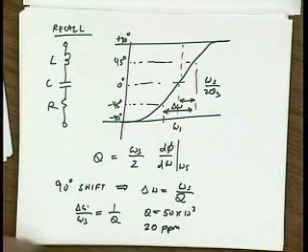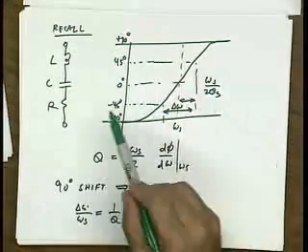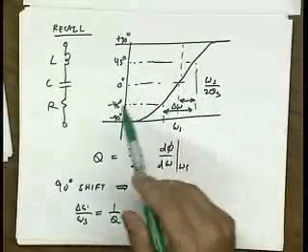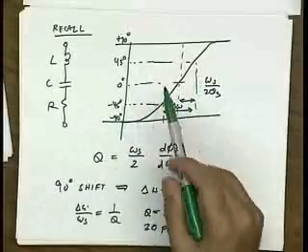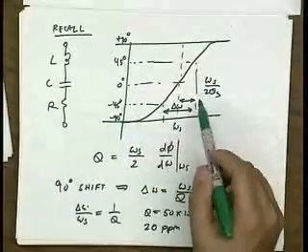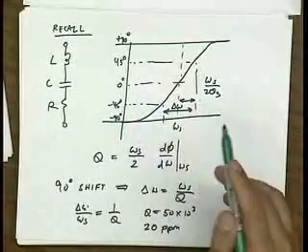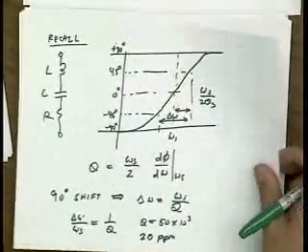So the nice thing is that if you build a circuit with this resonator, it's going to have extremely good phase accuracy regardless of any excess phase in your feedback loop. So you can be pretty sloppy in designing your circuits. It'll still resonate very close to where you think it should.